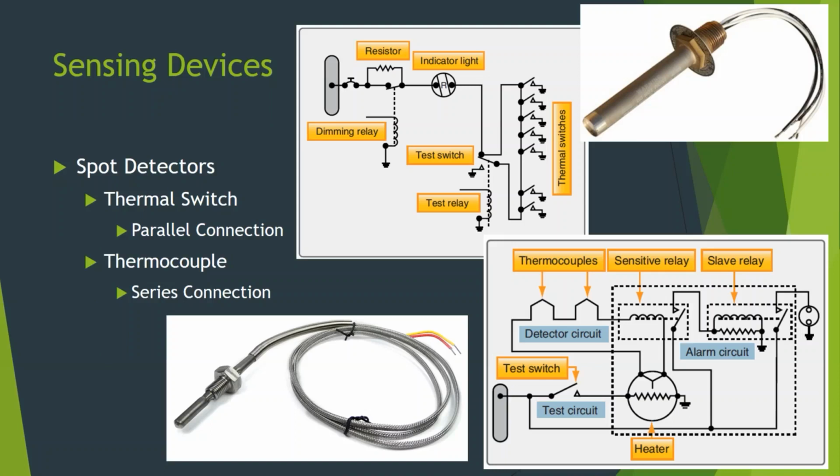Okay. We had bleed leak detection that were loop systems. One of them had 6 loops that went from the engines and APU at the back all the way up to the wing root, which meant they were in the aft equipment bay. They went underneath the cargo, which was behind the passenger cabin. They went underneath the cargo floor. They went underneath the passenger floor. They went up to the wing box. They came out into the gear bay, and then they went to the wing before it switched to the wing detection system. And they were all wired together.